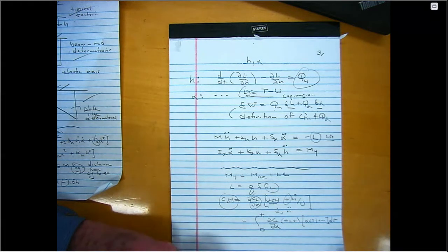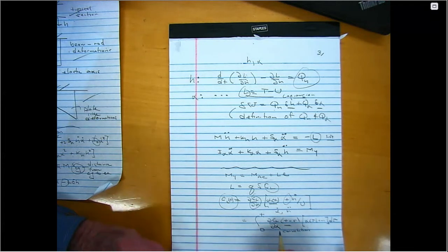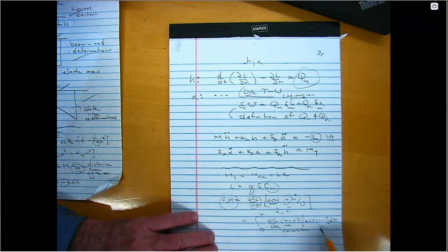What kind of integral is this? Convolutionary, right? Sometimes it's called a Green's function, sometimes it's called a convolution kernel, and it has various names in the mathematical and engineering literature. But physically, we're accounting for the fact that all the motion up to the present time can contribute to the lift at the current time.